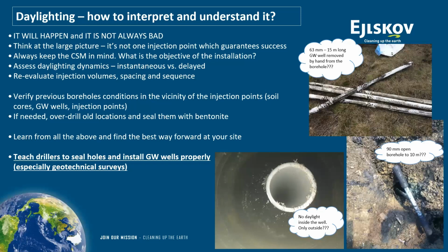And again, when you create fractures and you come into contact with those open boreholes, there's only one thing that can happen. So in short, every time we jump into a project, we try to make sure we have all the information about historical borings and where the site has been drilled, so that in case of future injections, we can always go back and trace locations, which may become troublesome.